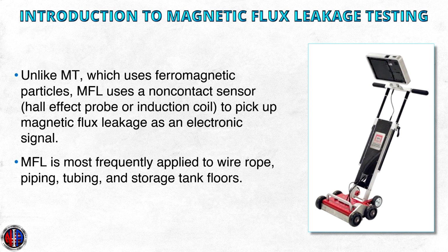MFL got its start from Elmer Speary's experimentations in the 1930s, in which he bridged U-shaped magnetizers with induction coils to inspect ferromagnetic materials. MFL technology slowly matured throughout the 20th century and was originally categorized by ASNT and other NDT governing bodies as an electromagnetic testing technique. It was considered an electromagnetic testing technique and not an MT technique because experts in the field determined that the magnetic field sensor, the eddy current induction coil, is the greater discriminator in classifying the evaluation technique.